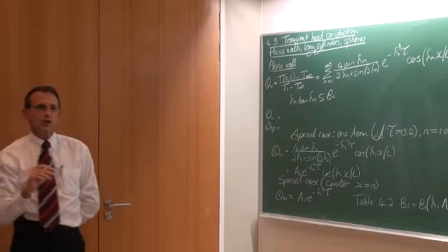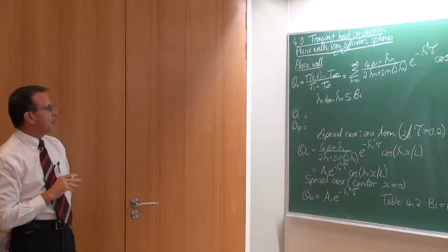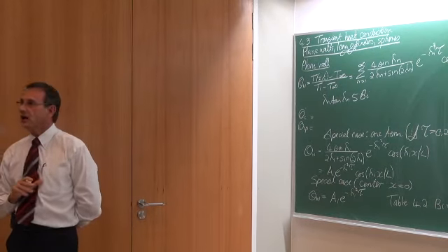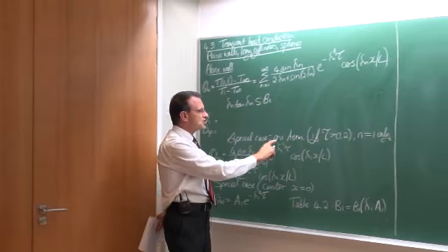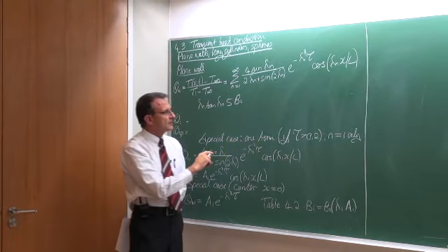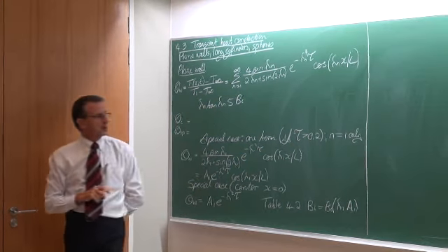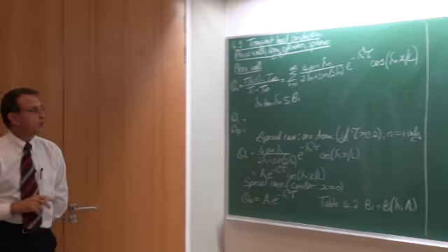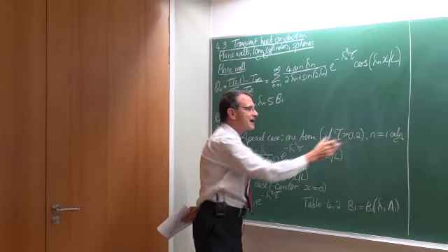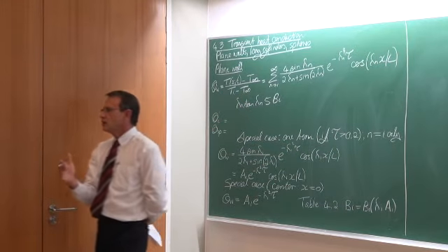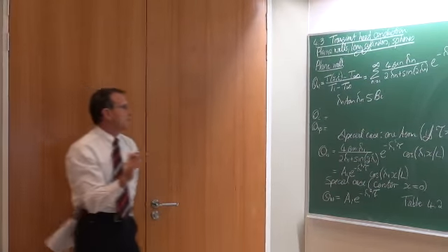It will take you maybe half an hour or an hour, and you can write out your own program. But there are 2 special cases. The first special case is to say, well, let's consider a one-term approach. And the one-term approach works well if the non-dimensionalized time is larger than 0.2. Okay, that would give us errors less than 2%, which for most engineering applications are good enough.